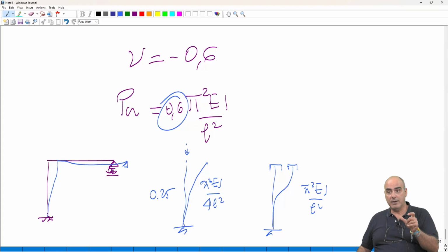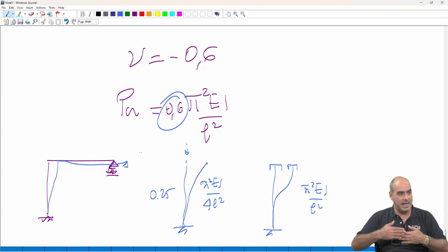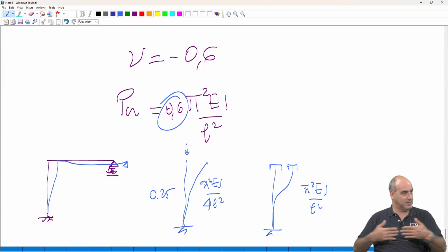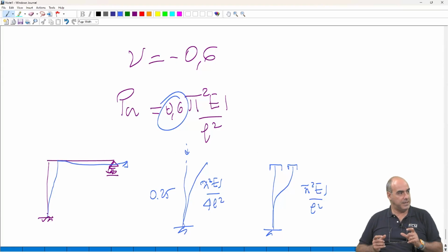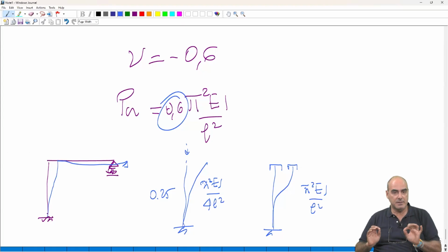So your design is still serial design and construction, but cannot be 100% serial, because you have to take into account my beam which arrives on one hand, probably reinforcement on one edge should be left, the reinforcement on the other edge should be right, because they have to arrive. So you have to shift this. You can have beams on the outer edge, beams on the inner edge. The reinforcement detailing may be different. So this is another aspect.